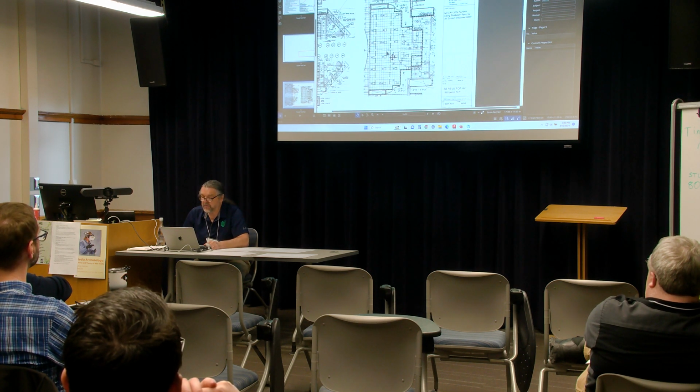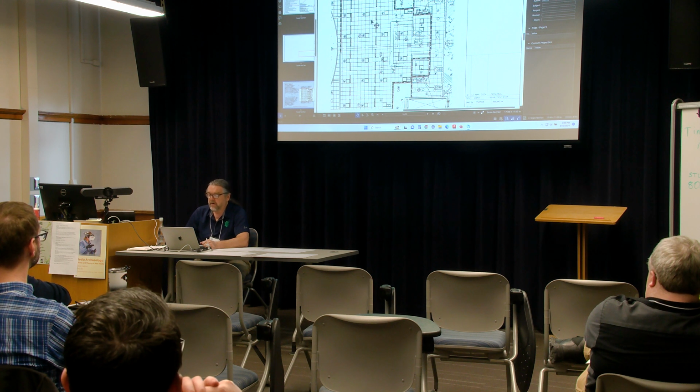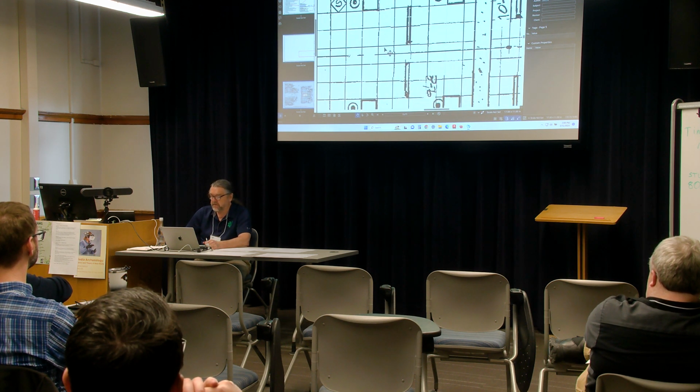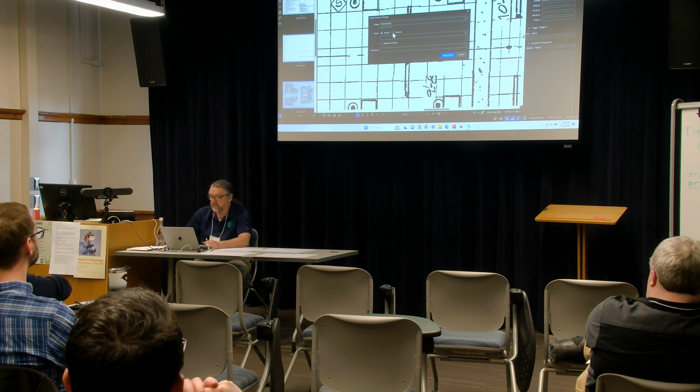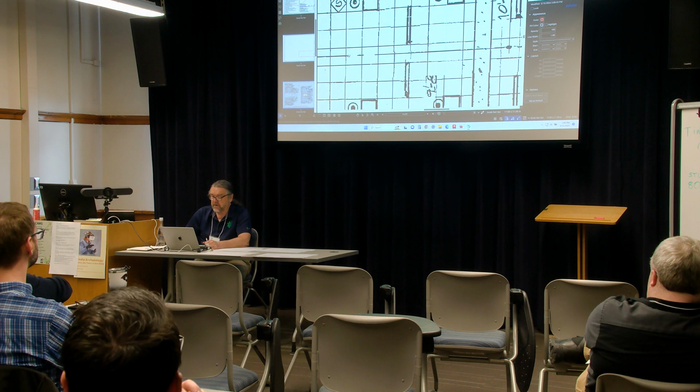One thing Bluebeam can do is, you were talking about using it to measure. And so how can we do that? Well, a 2-foot by 2-foot ceiling tile is 24 inches by 24 inches. So notice there's no scale set for this drawing, but I'm going to set a scale. And so I'm going to do a custom scale. And I am going to calibrate, and it says pick 2 points. So we know that this from here to here is going to be 4 feet.